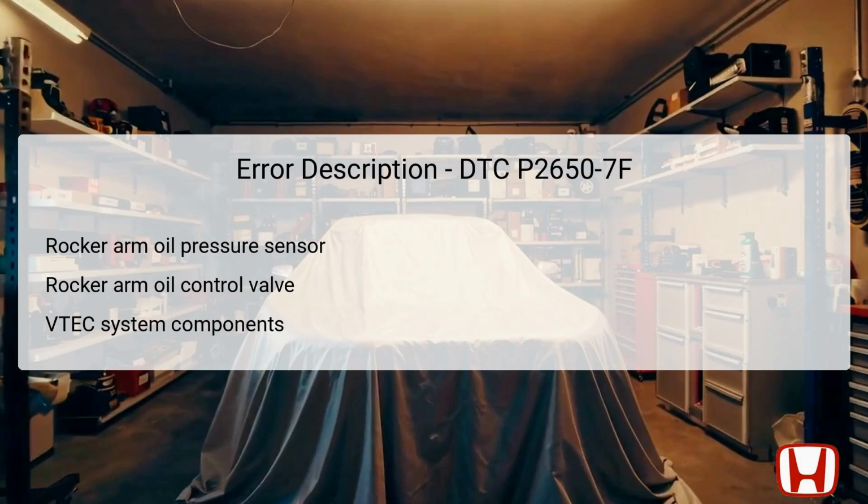Furthermore, the rocker arm oil control valve, which is responsible for directing oil to the rocker arms, also factors into this issue. If either of these components malfunctions or fails, it can significantly impact the VTEC system and subsequently engine performance.